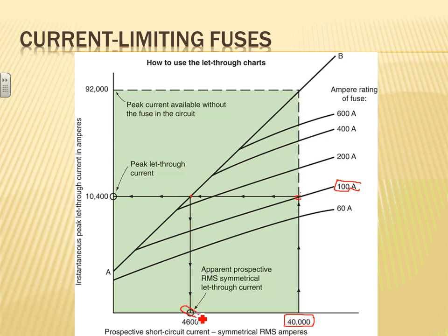So that's the whole advantage that I hear people use them for, to protect equipment, especially power electronics. Power electronics means a lot of things. What you end up doing is you continue with your circuit breaker coming in here, and down here you will have a fuse right next to the equipment, and that fuse inside the controller itself will be sized appropriately to protect your VFD, based on the withstand capability of the VFD.